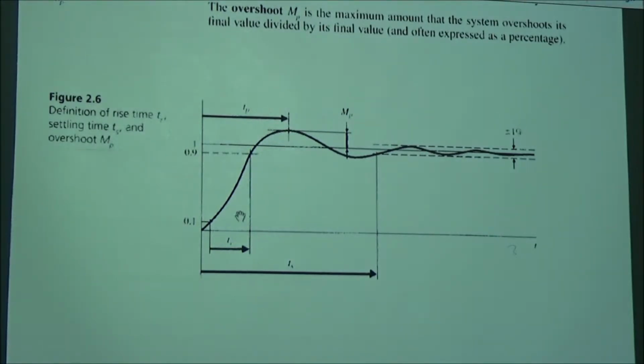And here you have, for example, the time going from 10% to 90% of the signal. This is called rise time. And the value of the maximum first overshoot minus the steady state value divided by the steady state value times 100% is called percent overshoot of the system. In general, you don't want to have any overshoot, because if you are reaching a destination, you don't want to miss the target and go beyond the destination.